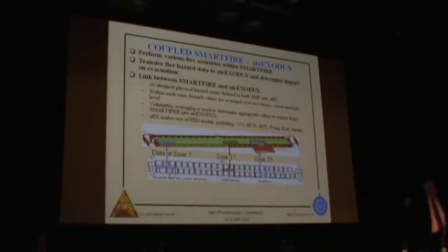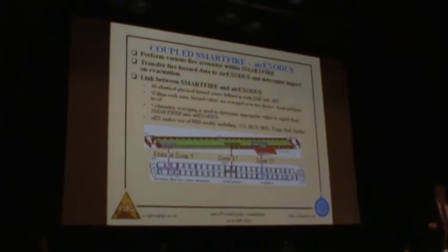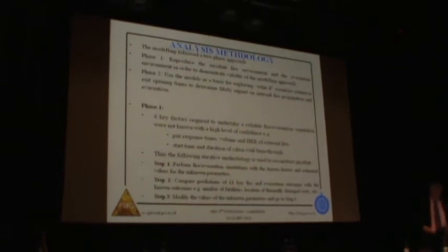The average values are at two heights, at head height and at knee height. Why do we have it at knee height? Because in these sorts of fires, the conditions at head height become so severe that people have to crawl to get through to an exit. So we have the toxic hazards and the heat hazards at both heights.